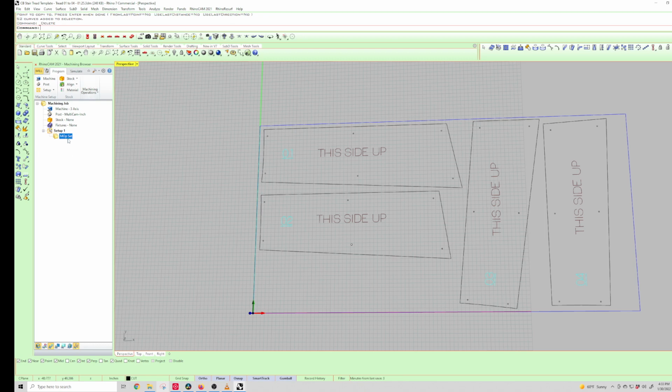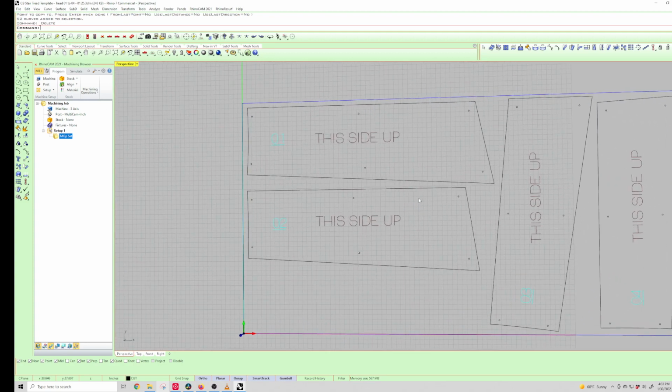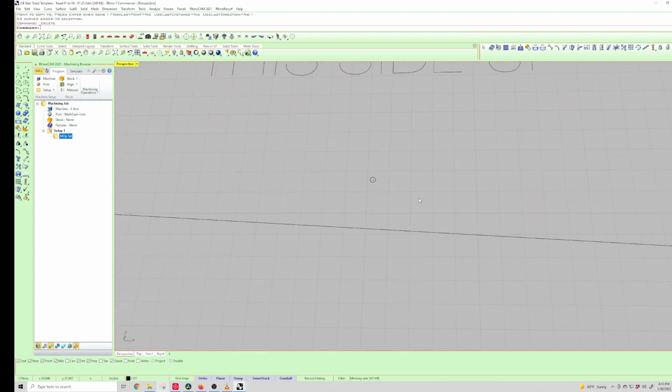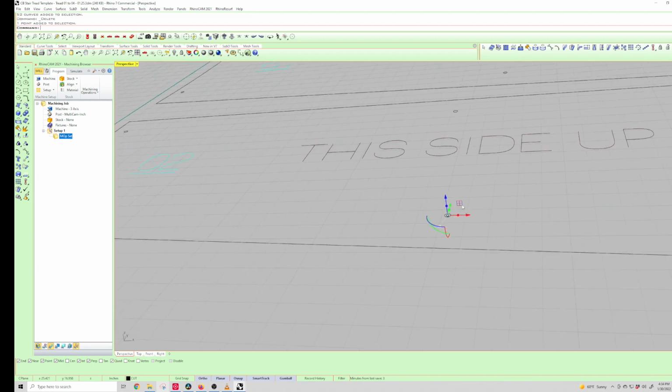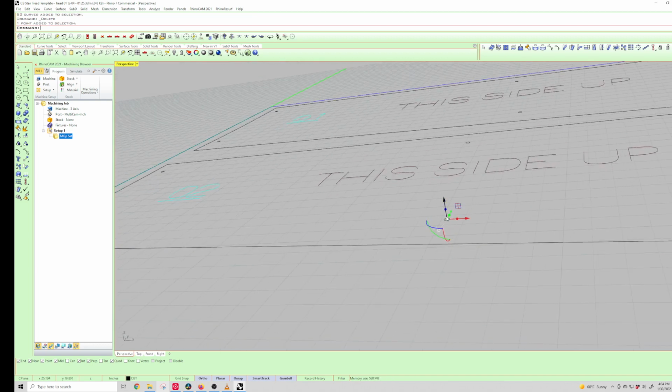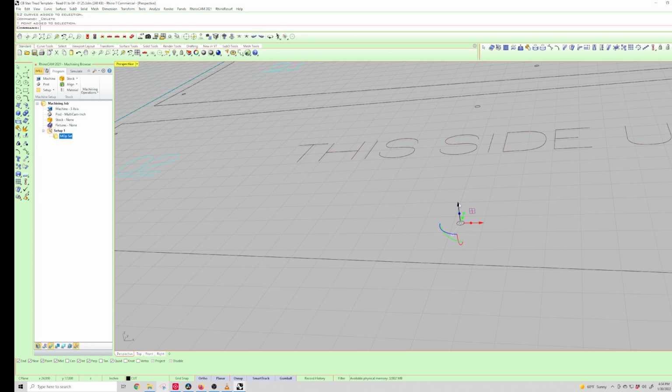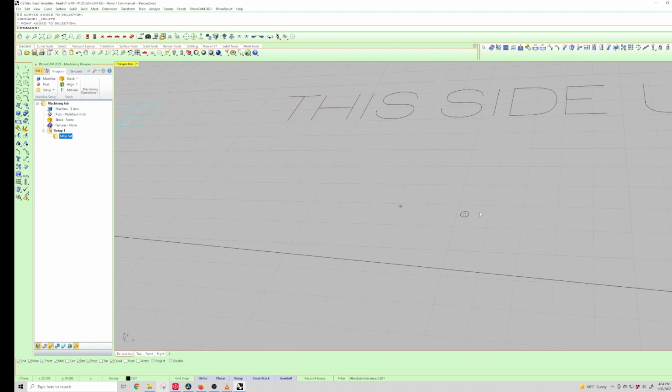So with this highlighted, the first thing that we're going to do now, and we're not going to do it in this one, or we don't need to, but with our program in the RhinoCam there's a pecking command, but we always use engraving, and we'll just use a dot like that, and we will engrave with whatever tool. So if this was a 1/4 inch hole, we would do an engraving pass and have it step down. We'll go through the process on that just to show it.